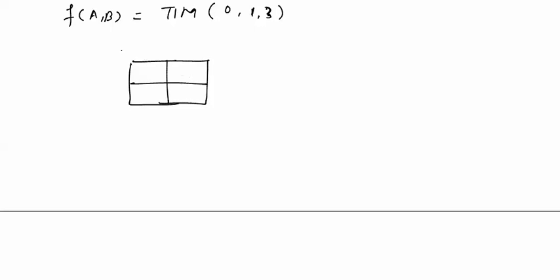The expression will be obtained in POS form this time. 0 1 0 1. Remember one thing, that for a POS expression this 0 will represent B and this 1 will represent B bar. This 0 will represent A and this 1 will represent A bar.